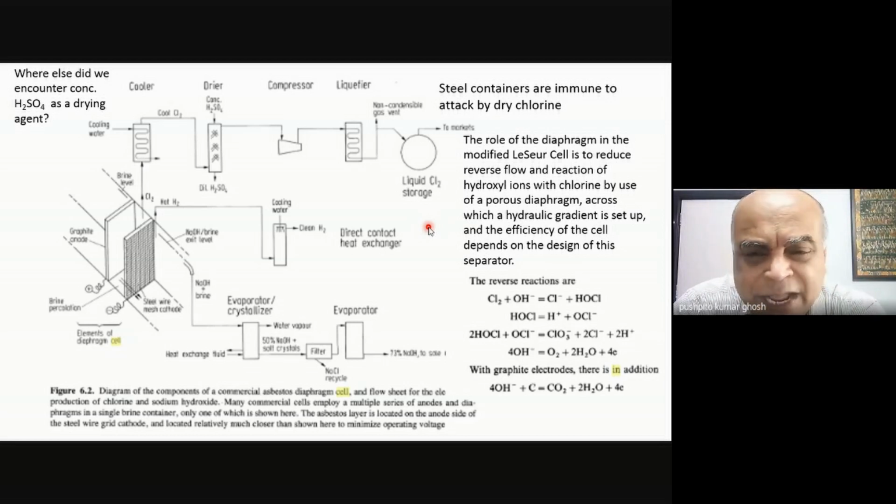And even to this day, all of us practice that. All the chlorine goes in that manner. Here, of course, they had to carry out the evaporation and purification. The sodium hydroxide has a high solubility, and sodium chloride solubility doesn't change at all with temperature. So as they were evaporating the water and making the sodium hydroxide concentrated, the sodium chloride was falling off, and that's how they ended up making a relatively pure sodium hydroxide, but obviously it was still quite contaminated.